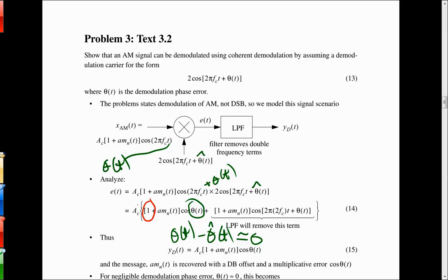Or perfectly not? 0. What the model could be is that it's just rolling. It's like the two waveforms are just sliding past each other, or they could be sliding very rapidly past. That would be a frequency error if phase is linearly changing. That's going to become more apparent later, but phase and frequency are derivatives or integrals of each other.